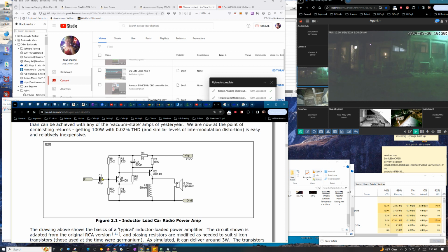In fact, I've seen it when people take two electrolytic capacitors and put them back to back, like 10 microfarads back to back with another 10 microfarads in the other polarity, to make an AC electrolytic capacitor, which supposedly is what those motor start capacitors and motor run capacitors are. You see that they're clearly electrolytic because their value is too high, too many microfarads to be anything else, but they're not polarized, they're for AC. My understanding is they do them that way. They actually have two electrolytics that are back to back like that.